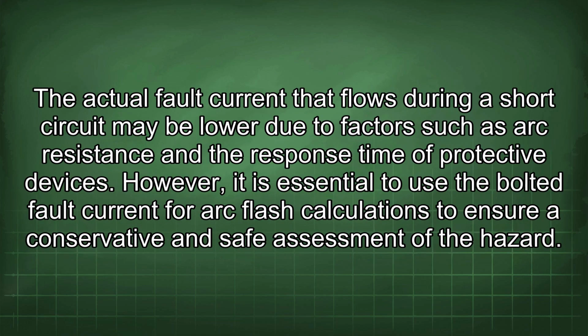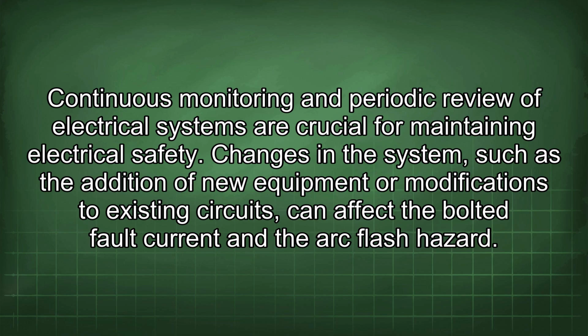It's important to note that bolted fault current is a theoretical maximum value. The actual fault current that flows during a short circuit may be lower due to factors such as arc resistance and the response time of protective devices. However, it is essential to use the bolted fault current for arc flash calculations to ensure a conservative and safe assessment of the hazard.